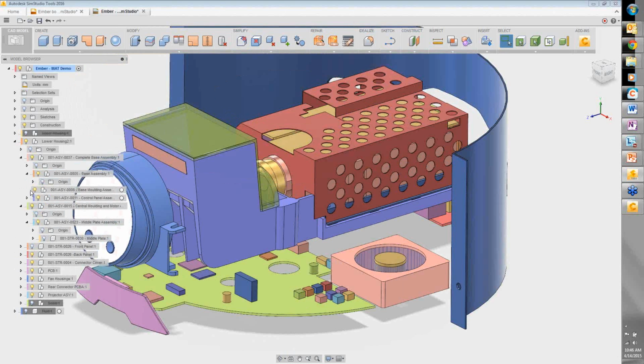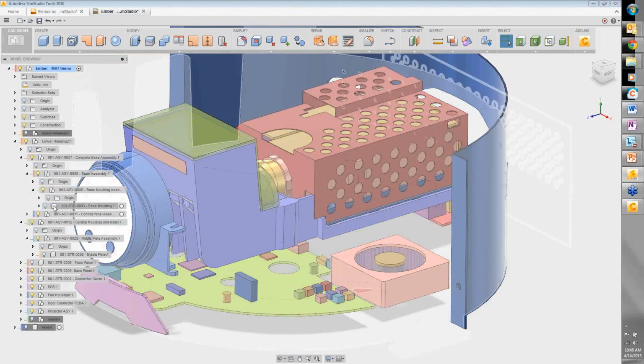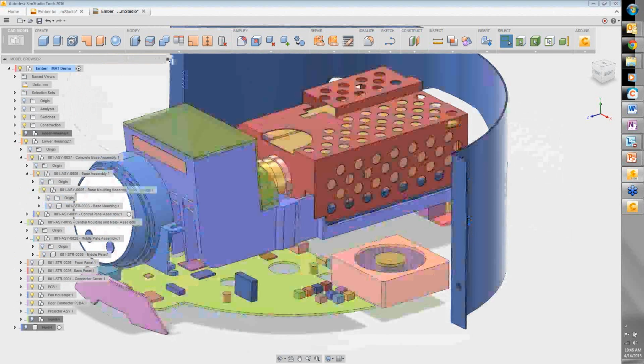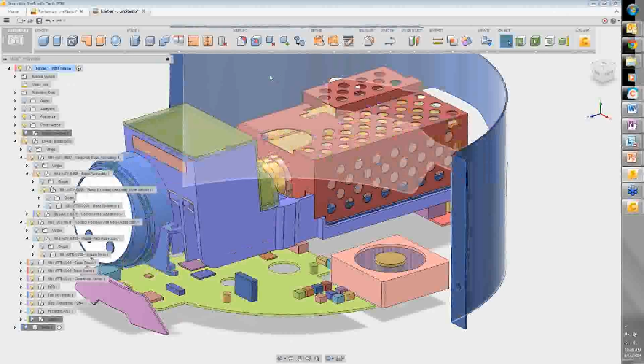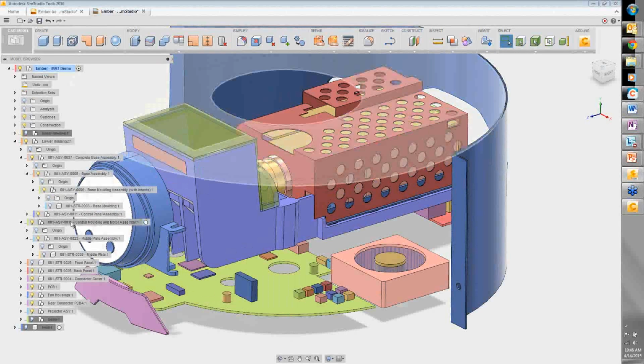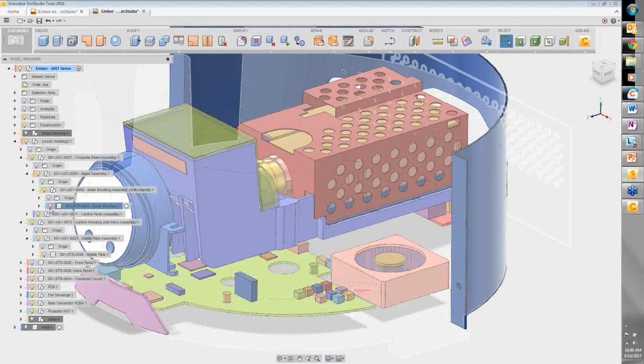So if you have a really complex assembly, what you might get is stuff that didn't come over properly. We have a bunch of surfacing tools within here for repairing and auto-fixing, and it can become real handy when you look at a model and think, that is not what it should look like. Be able to delete, restitch, and use gap fill and stuff like that. It was really beneficial for me.